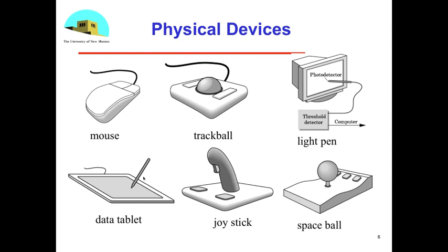On the other hand, a data tablet, which is sort of the predecessor of the touch screens you have now, has usually two-dimensional wires underneath it, and by putting signals down those wires at a known time and measuring with the stylus the voltages or some sort of property that comes out, you can get the absolute location of where that is. So here's an absolute positioning device, and that's become the touchpad that we have now. The technology's changed, but what's stayed the same is that wherever you put that stylus gives you an exact position.